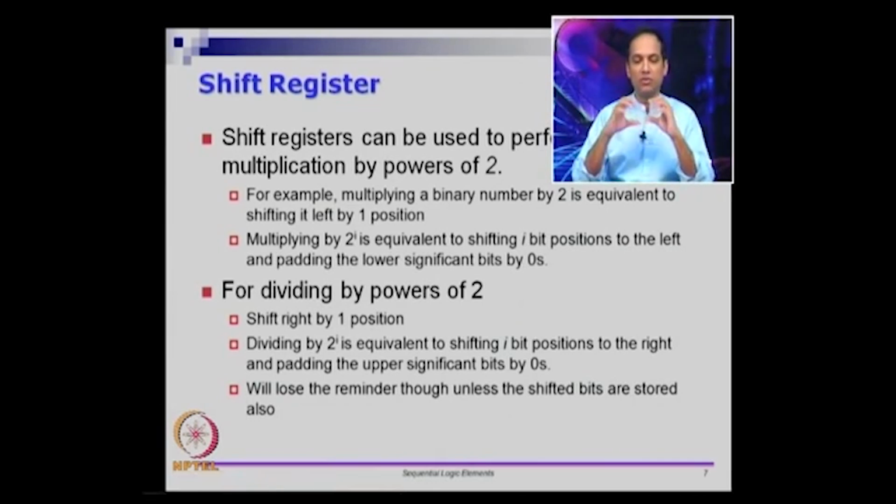So if I put some value n in a 5-bit register, and I right shift it 2 times, the equivalent value will be n divided by 4, or the lower, so you know the ceil and floor functions, right, it will give you floor of n divided by 4, which means the integer that is lesser than n by 4 and the closest to it.